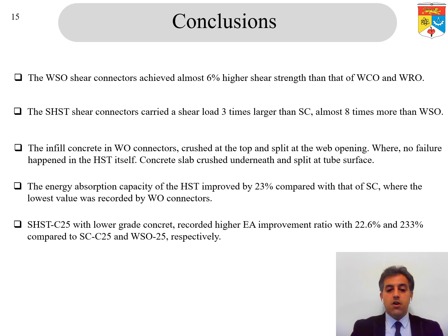A square shape of hollow steel tube connector with the lower grade concrete of 25 MPa records a higher EA improvement ratio, 22.6% compared with the shear stud and 233% compared with the web square shape of opening.